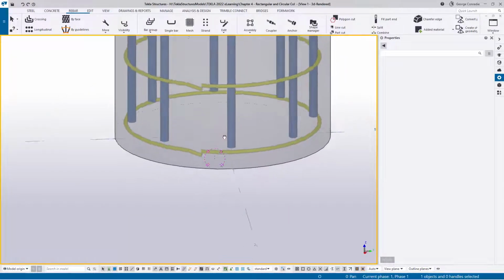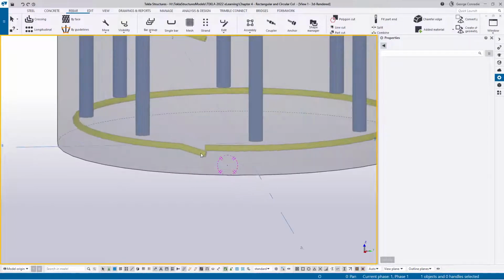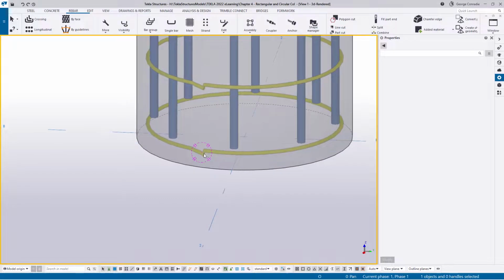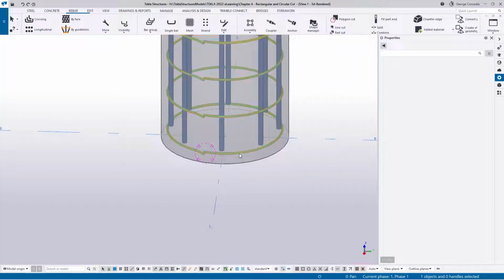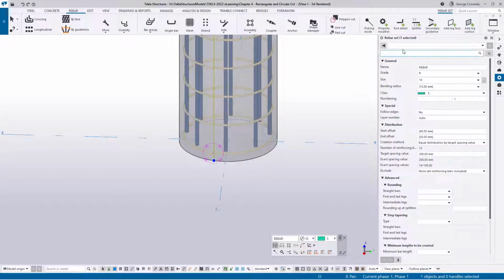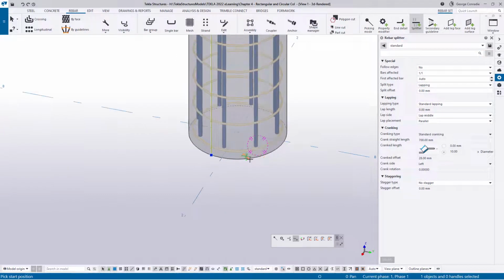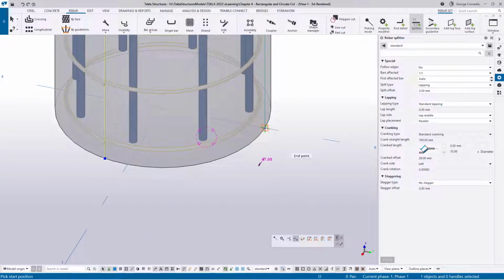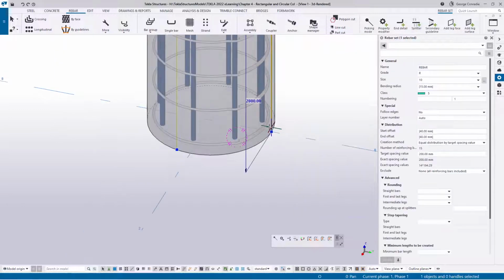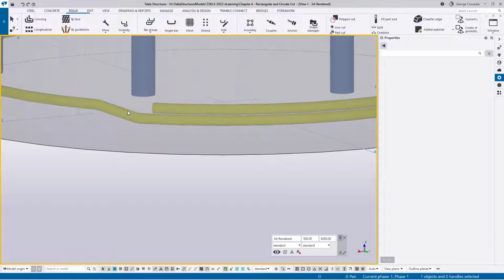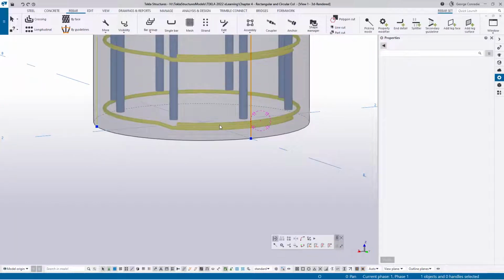But the first thing you notice is it's got a bit of a step down here, like something is happening there. It actually affects the rebar shape. If we click on this and introduce the proper splitter, the splitter I'm going to introduce is our normal lapping splitter for that bar diameter. And I'll just hover over an edge here. You can see it does a pretty good job of splitting the bar and lapping the bar. But again, we're dealing with this kink here. It's almost like a crank rather than a proper lap, and it does affect the shape of the bar.